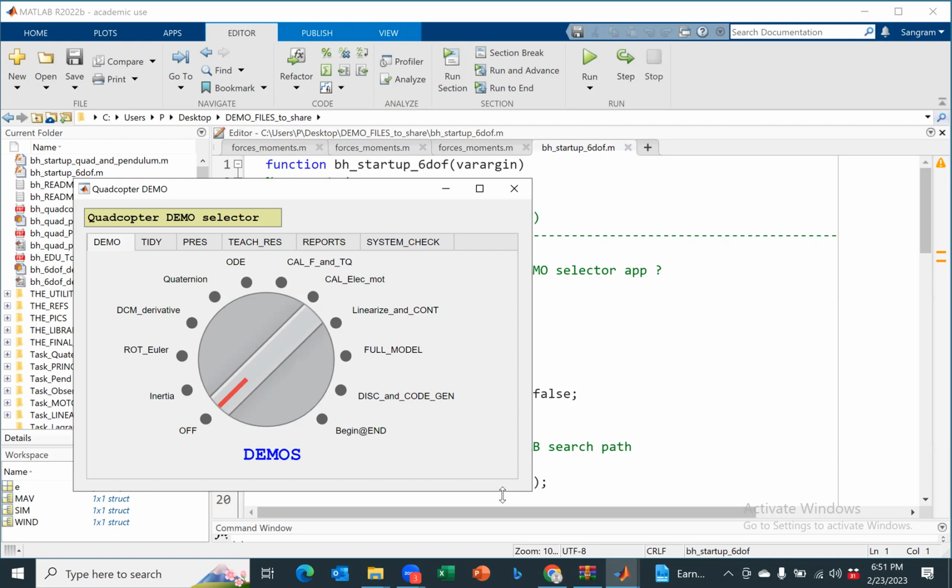If the aircraft is not going to do 90-degree pitch, then you are fine with Euler. If your aircraft is going to perform super complex maneuvers, or if it's going to go to 90 degrees pitch or come back or flip, so the flip means basically aircraft goes to 90-degree pitch. That is also a dangerous condition, because please understand, we are working in discrete time. So even though the aircraft is at 90 degrees for a very short period of time, that will give an error in the actual computation, and it will give you some type of exception in the processing.